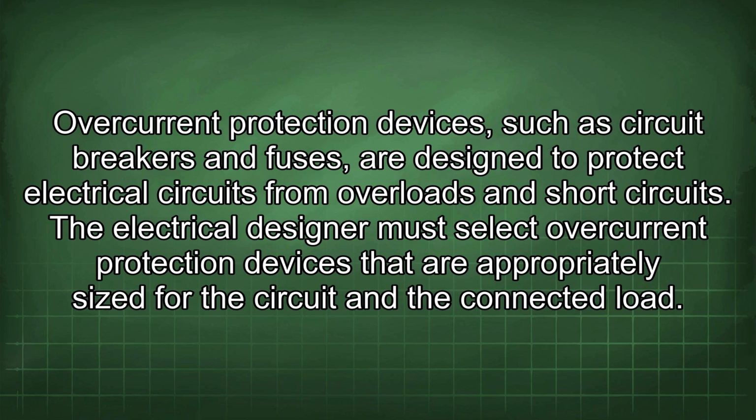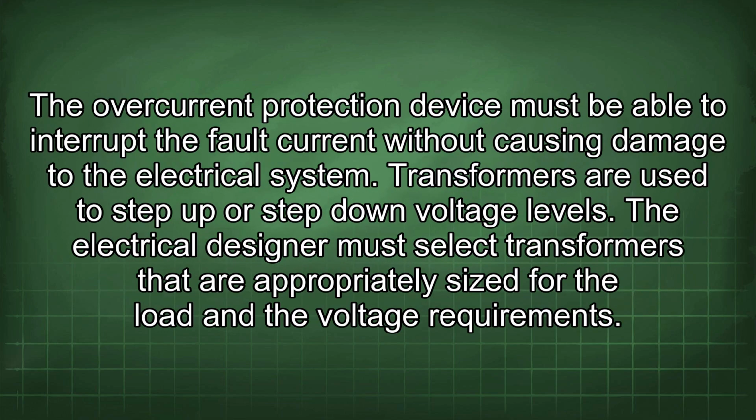Overcurrent protection devices, such as circuit breakers and fuses, are designed to protect electrical circuits from overloads and short circuits. The electrical designer must select overcurrent protection devices that are appropriately sized for the circuit and the connected load. The overcurrent protection device must be able to interrupt the fault current without causing damage to the electrical system.